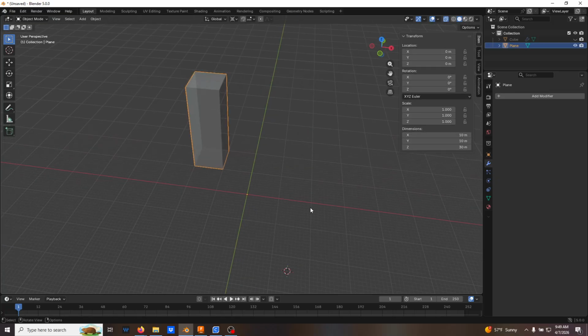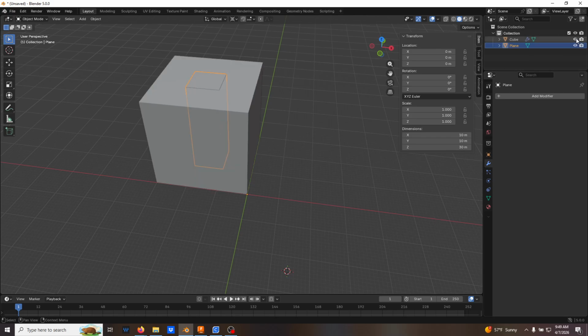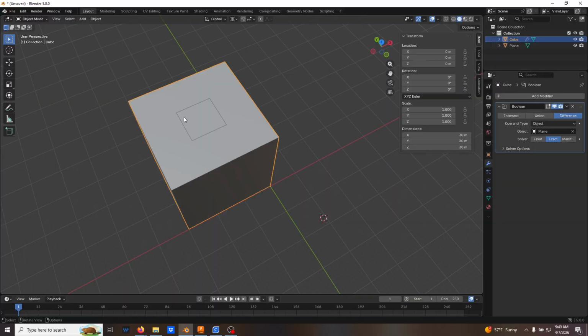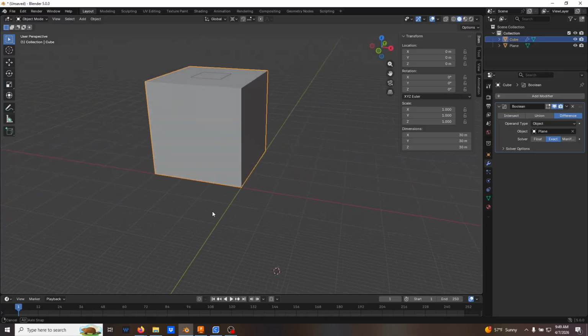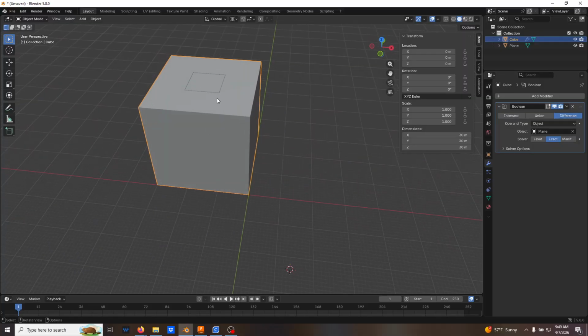All right. So now if I tab that out, turn X-ray off, and turn my cube back on so my modifier is in there, you'll see that it does a little weird thing with the Boolean, because those faces are right on top of each other. So when you're working with this stuff, you want to be mindful of where things are sitting on top of each other, because they can kind of screw the math up. One of the reasons I extended those paths was to make sure that the Boolean wouldn't have any trouble. I could work with it as is, but you want to be mindful of that whenever you're working with Boolean modifiers. Combinations, intersects, unions, all that stuff is a good way to make your models, but just make sure you have some overlap, because without getting into it more than I already have, it makes the math easier.